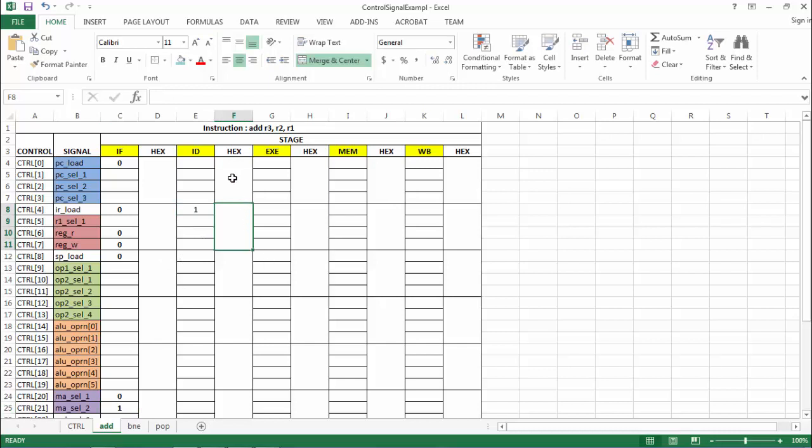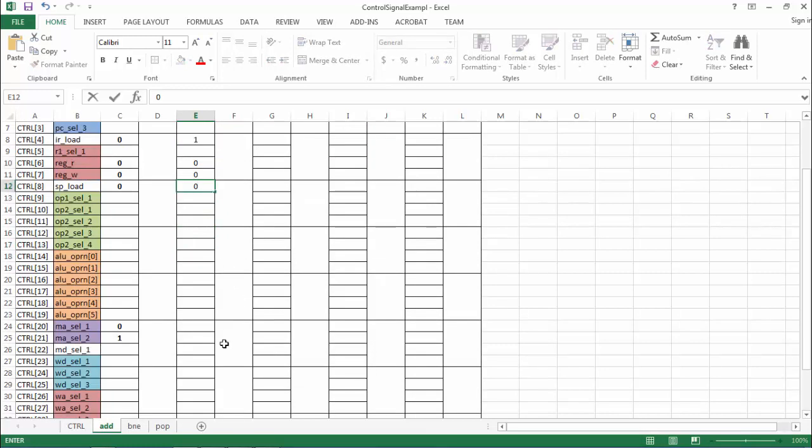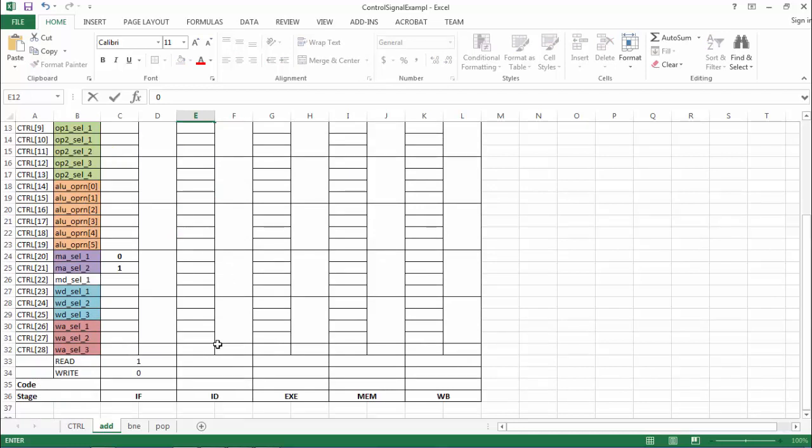Okay, and we don't want to override the PC, we don't want to override the registers, we don't want to override the stack pointer. At this point, since I have already read from the instruction memory, I can make this a hold configuration.